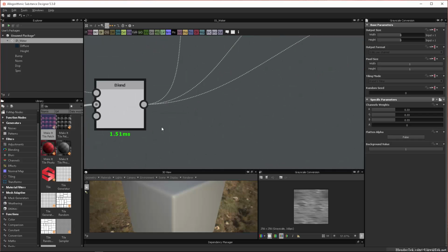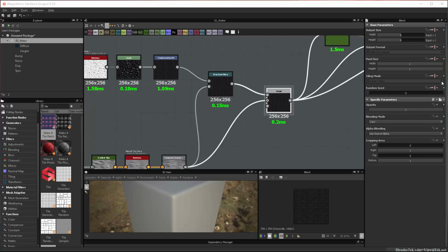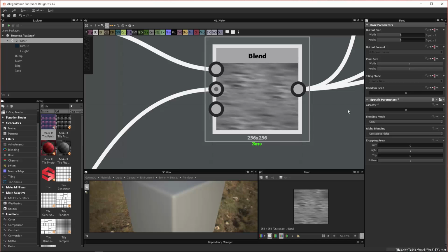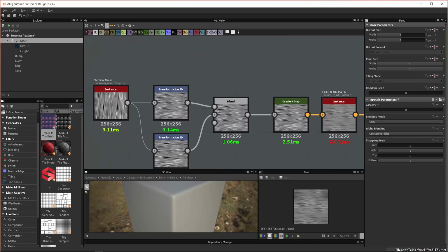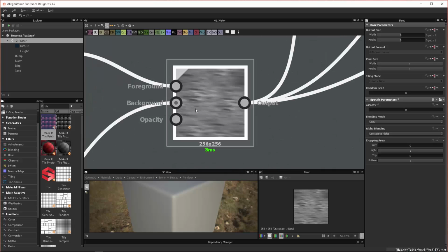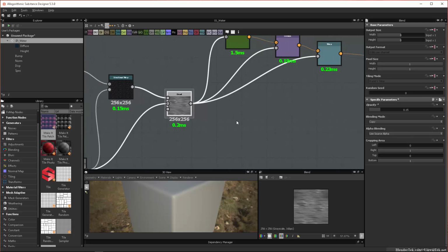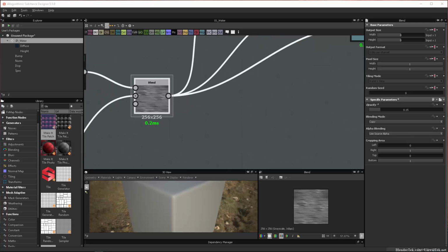So now to get the rest of our maps, we're going to work off of the blend. Now comes into play our blend node. We want to turn the opacity down so it's not so much of the cells, but it's not totally the, what the heck do you call it? The vertical noise, right? I thought it was horizontal because I flipped it. We want it mostly the vertical noise though, with a little bit of the cells in there. So a pretty darn low value. I'd say somewhere about 0.10, 0.15, somewhere in there should do all right.